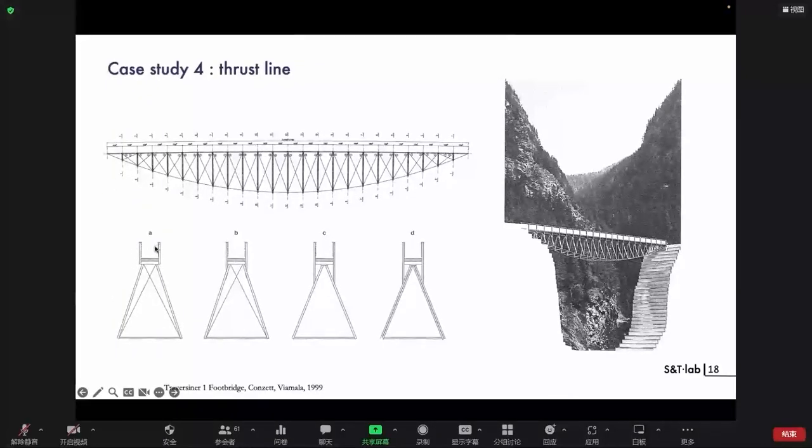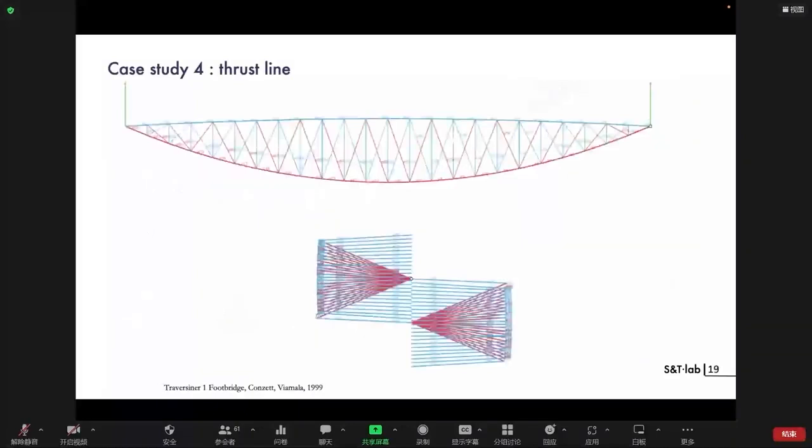And the four sections that you see show the development of the cross-section of the bridge, mainly the connection between the balustrade and the substructure. So the deck is made of horizontal glulam beams and suspended with steel cables. If we look at the analysis with VGS, we can see the parabolic form that gives an advantage because the diagonal members are almost stress-free under permanent load, making them easy to replace if necessary because of the weather, again, in Switzerland.